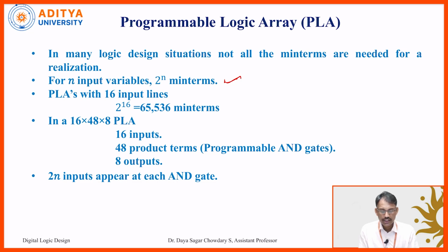PLAs with 16 input lines. If 16 input lines are there, definitely 2 to the power of 16, that is 65536 minterms we can use. In a 16 into 48 into 8 PLA, this is the representation, means 16 inputs and 48 product terms and 8 outputs are there in this particular